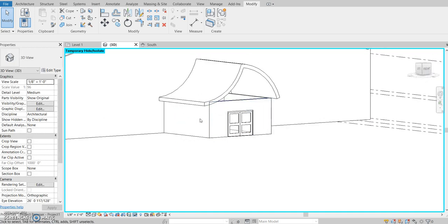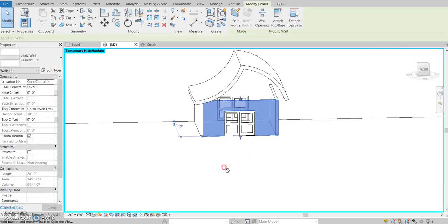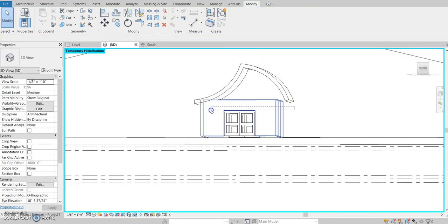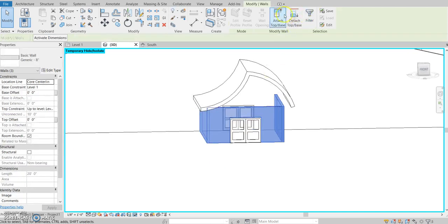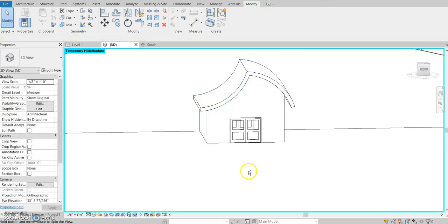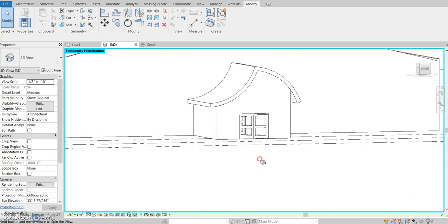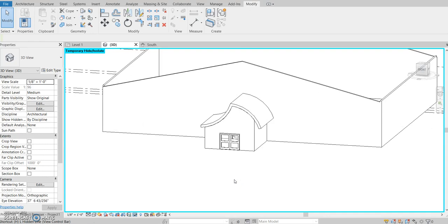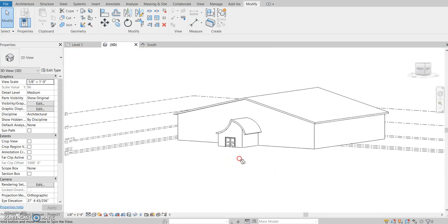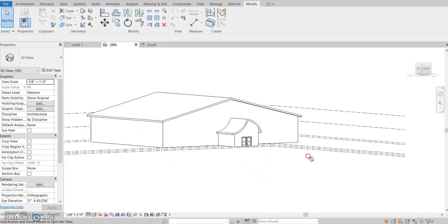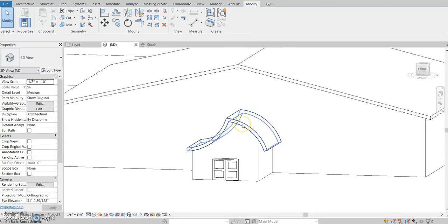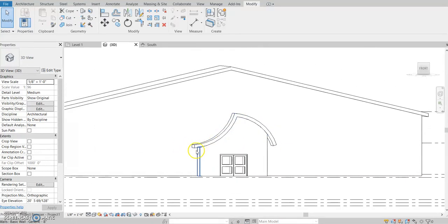And so then from there you can click your walls. I'll just do this real quick. Click your walls and then attach to top, and there you have a funky little roof. And you can do that for a lot of different implications. I think my favorite one personally right now is just a simple arched roof.